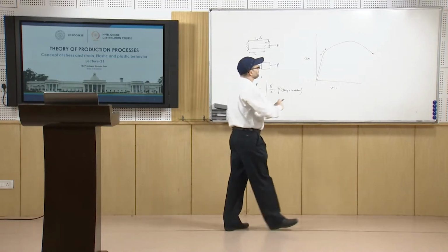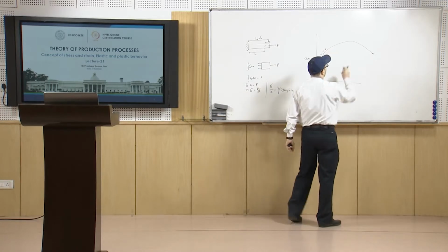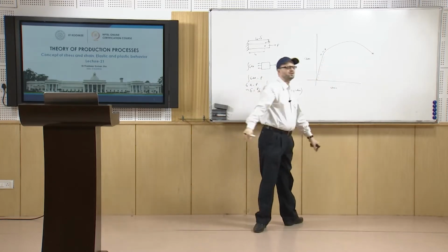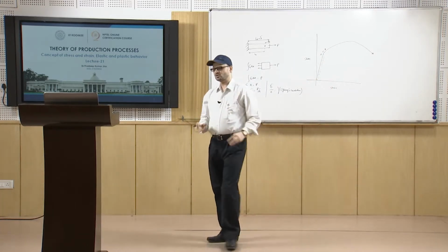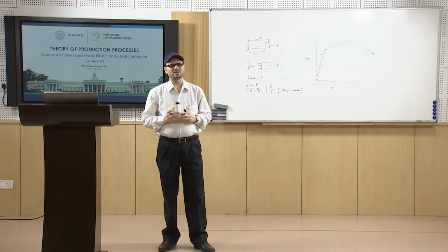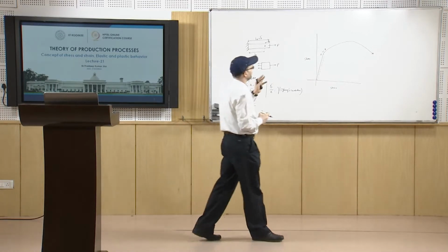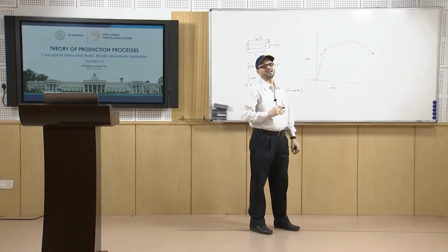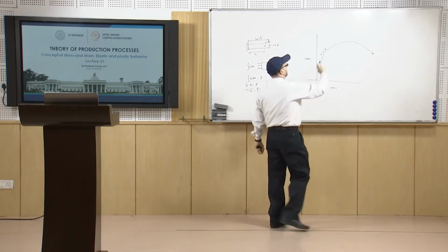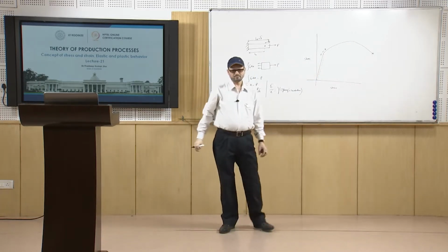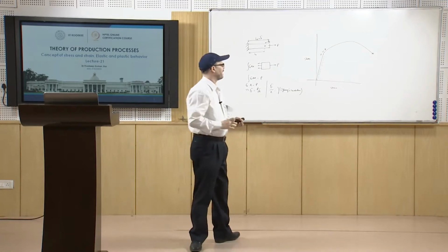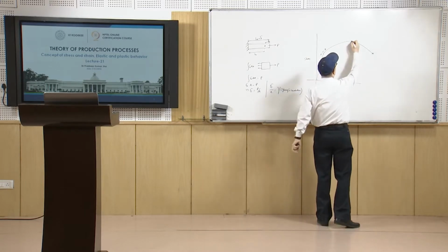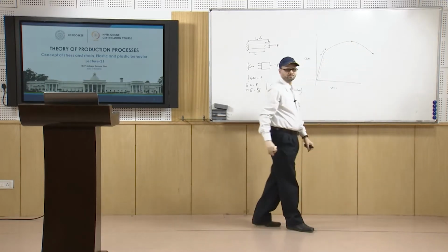Now, after that the deformation starts increasing, and the strain goes on increasing. What happens during this stage? There is strain hardening going on due to the plastic deformation. As the plastic deformation goes on, strain hardening takes place. Because of that, the stress value goes on increasing, so the load is increasing, and you come up to this point where it is maximum.